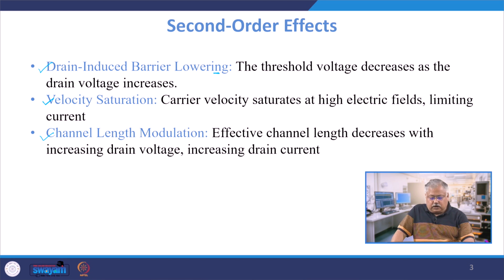First of all, what does the first one tell you? I will just give you a small brief insight rather than going into details of it. It is drain induced barrier lowering. What it means is that as you start reducing the dimension of the device or the channel length of the device, you are effectively bringing the drain closer to the source, right. And therefore, the drain starts to have a larger impact on the profile as compared to the gate, because now the drain is coming closer.